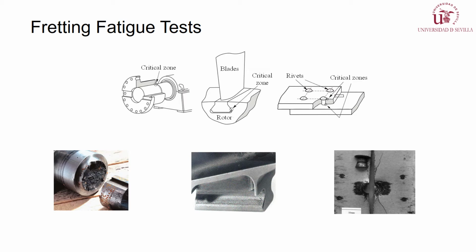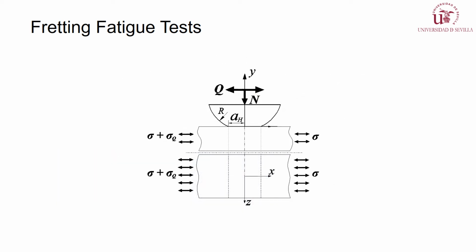Due to the presence of a tangential load and considering the stiffness of the contact pair, in some practical cases a small rotation can be produced between the mating surfaces. Although cylindrical contact is not the typical setup used in engineering components, it is a widely used contact pair in fretting fatigue tests. In this type of contact pair, the rotation leads to a small rolling between surfaces, this effect being more or less important depending on the contact pair stiffness.